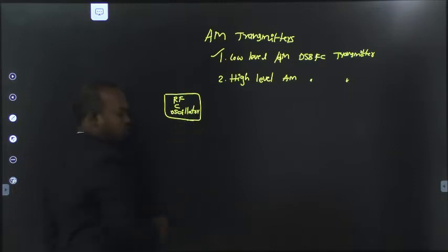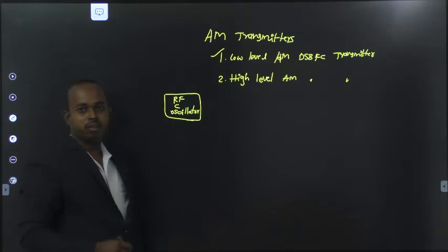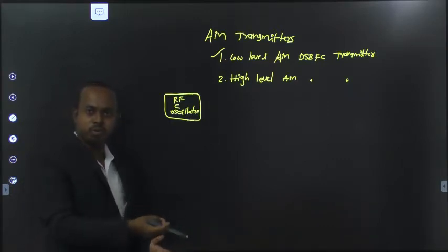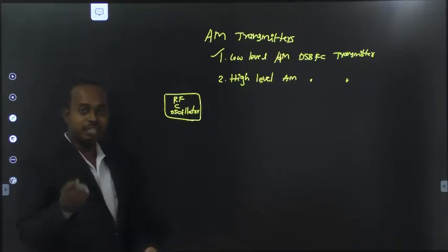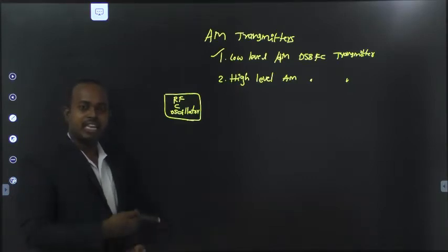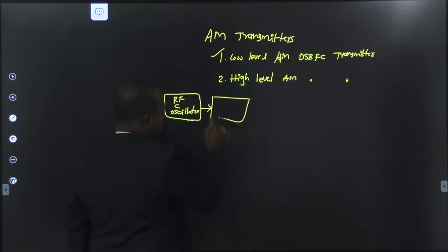The RF carrier oscillator generates the radio frequency signal. Simply remember that an oscillator means, without any AC signal input, it produces an AC output. Here we are using the RF carrier oscillator. The device generates the RF, that means radio frequency, carrier signal. The radio frequency carrier signal of the RF carrier oscillator we are assigning to the buffer amplifier.